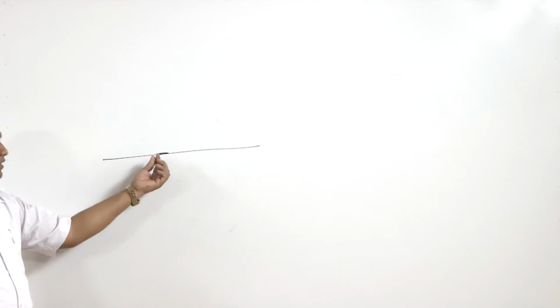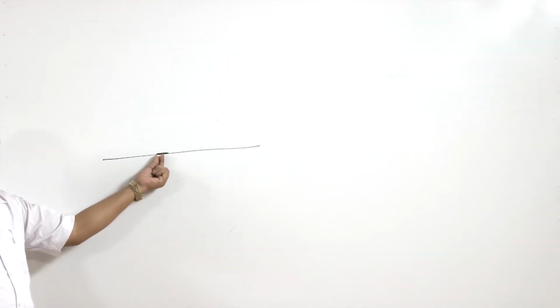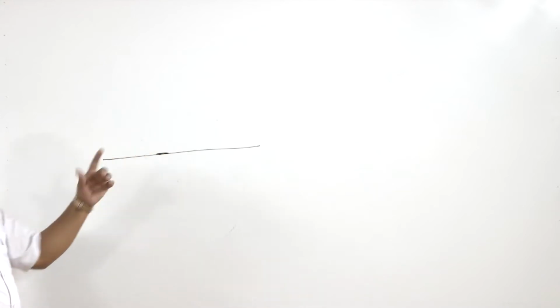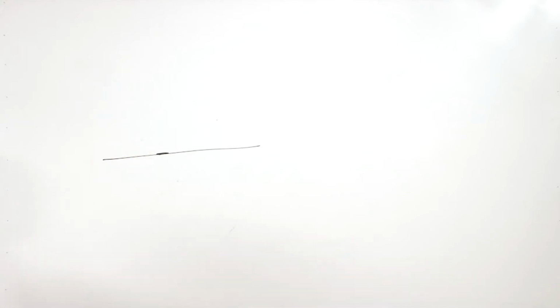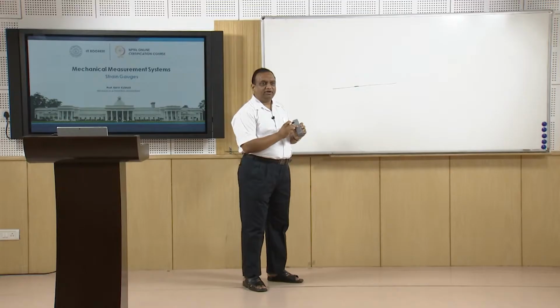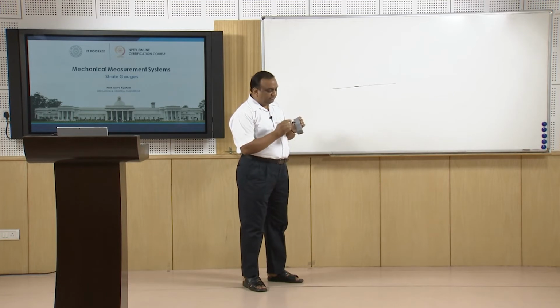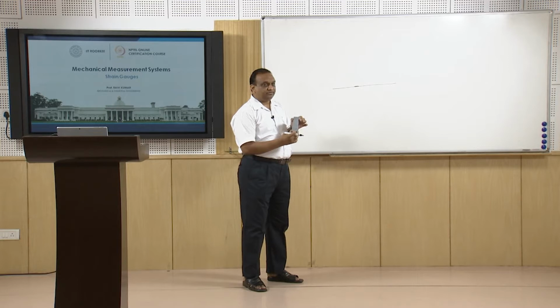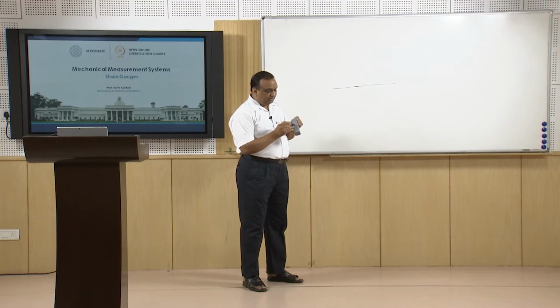So, once I am able to calculate the strain developed in the strain gauge on any substrate, for example this duster, suppose I put a strain gauge here and put it under tension or compression, the level of strain is the same, because strain is dimensionless. So the strain in the strain gauge is equal to the strain in the duster.